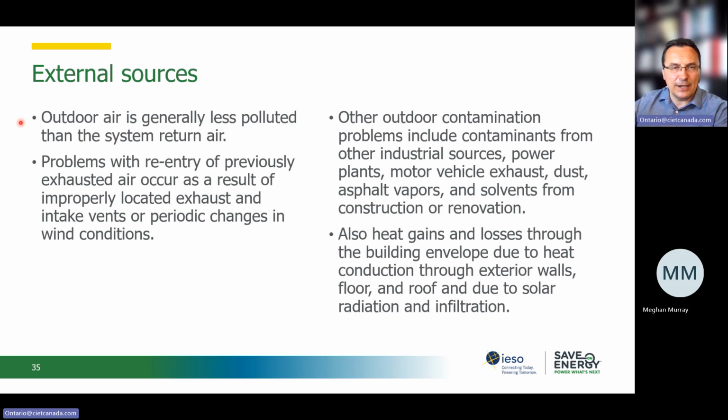In many cases, if you are in a very high traffic area, or let's say the design of the HVAC system placed the intake of the fresh air near a loading dock, you may actually see issues with the fresh air being more polluted than the actual air in the space.